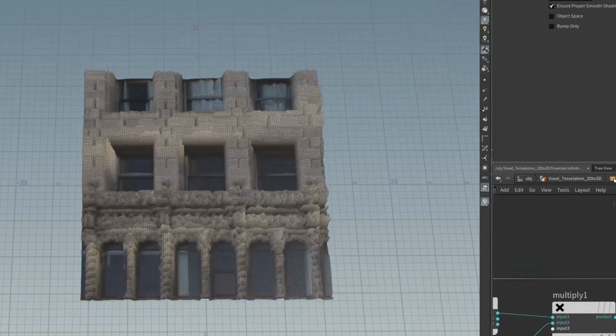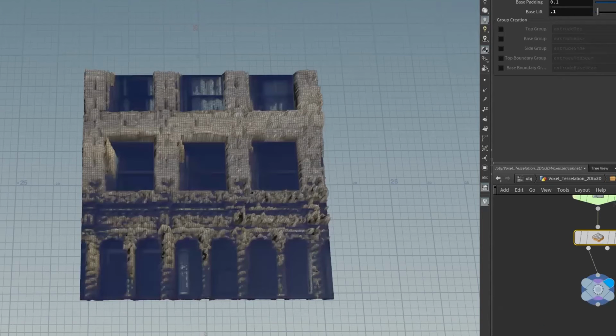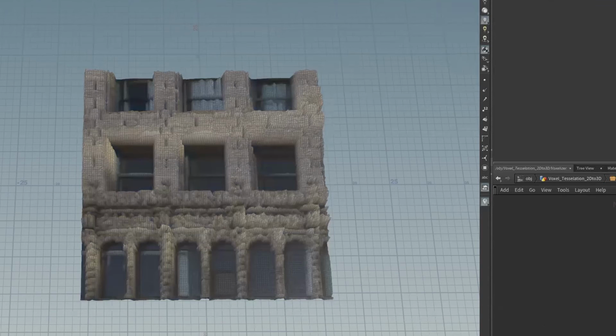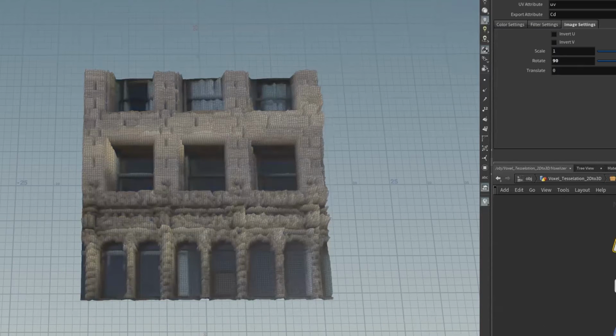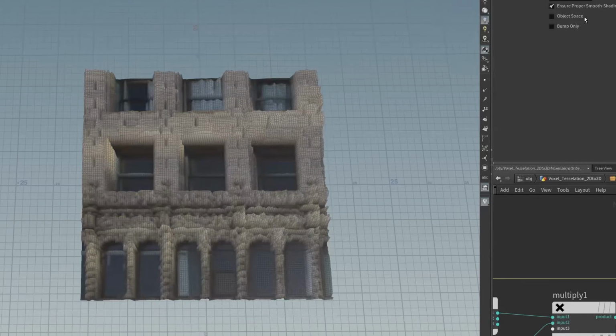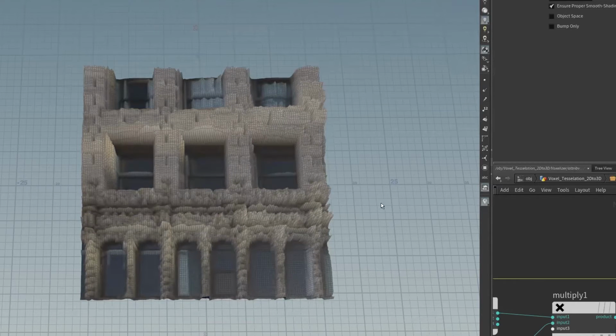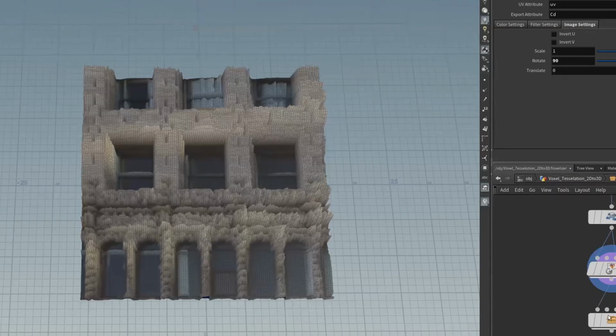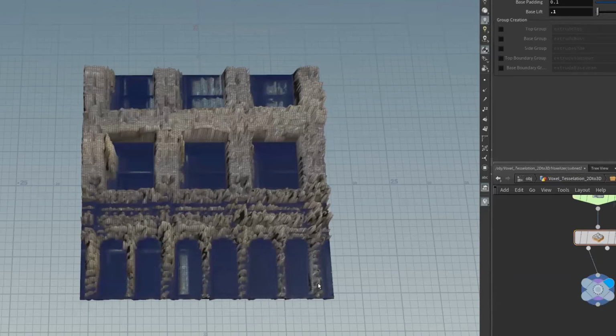I'm going to do 5, okay? And go back here and see if you're missing any geometry. It looks like you're still missing some geometry, so go back here and set it to maybe 7. It's going to make it better, hopefully. Yeah, now we're catching most of the geometry. So for now, let's say I'm happy with this result. You can fine tune it on your own, okay?